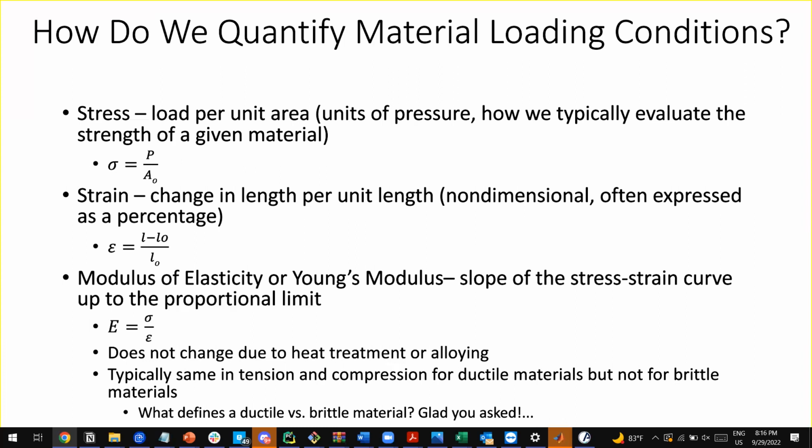The most fundamental concept in solids is that stress, my normalized description of the loading the part is undergoing, is related to strain, my normalized description of the displacements. Fundamentally, everything behaves elastically. There's a relationship between how much stress, or force per area, I put on it compared to the relative displacement.